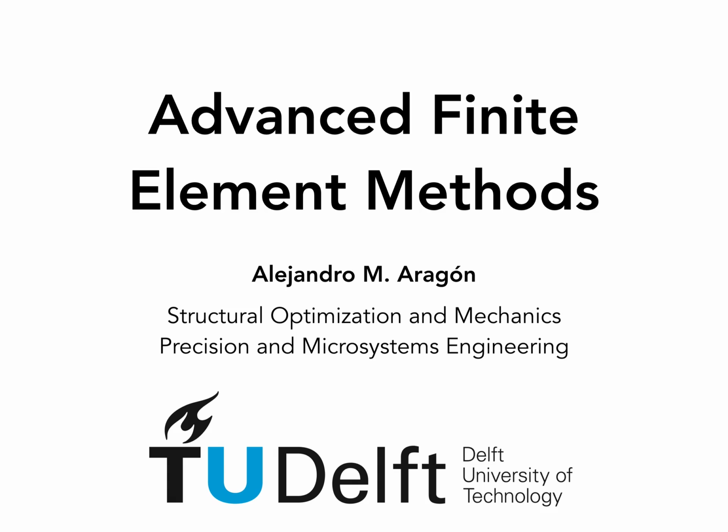In a way, my objective for you is that when you go out and use a finite element software, most of you will probably do that or have done that already, you don't treat this as a black box, but you really understand what is happening behind the scenes. And you will be able to do that because you are going to be given a finite element code from me, and then you're going to understand exactly every step of the process, from reading the input that is required to run a finite element example, through the assembly procedure to get your system of linear equations, and then the solver, and then the output, so you can actually visualize the results. That is basically what the finite element code is all about.